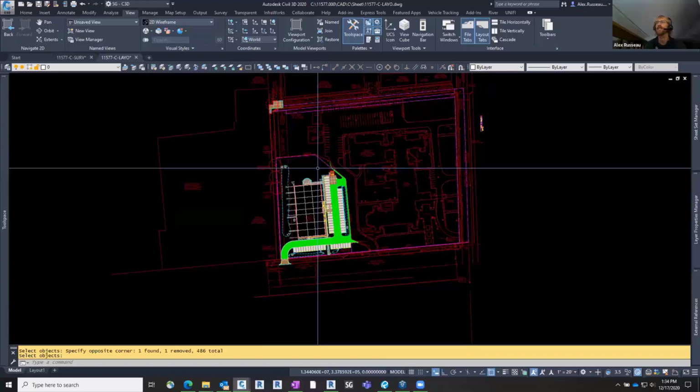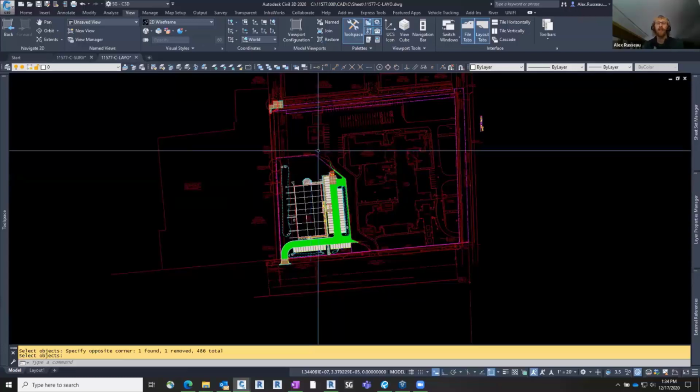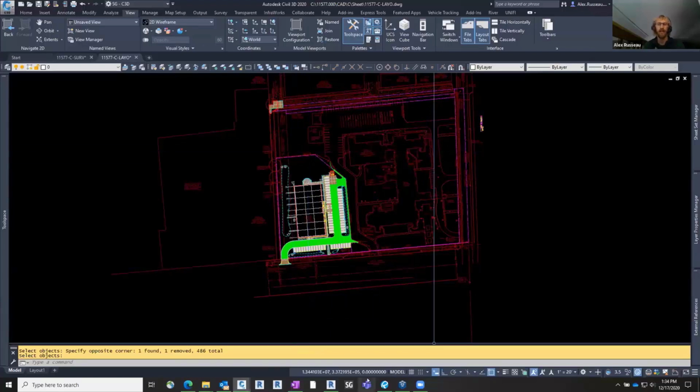I'm going to interject here because it's one thing that I've really liked about how you disassociate the 3D topography from the Civil 3D link. That way you can control those separately. So the line work is one thing, and that's at the flat level, and then the 3D is at a separate link so you can turn things on and off. Yeah, and we've gone as far in our world as creating two files. We've had one that's just line work, and we've had one that's surface elements. That does give you a little bit more control, and I think that might have been a little of what Nick was talking about too.